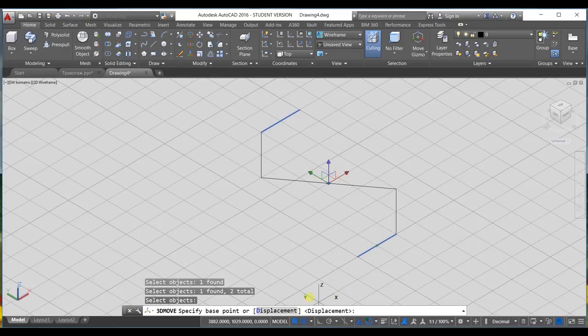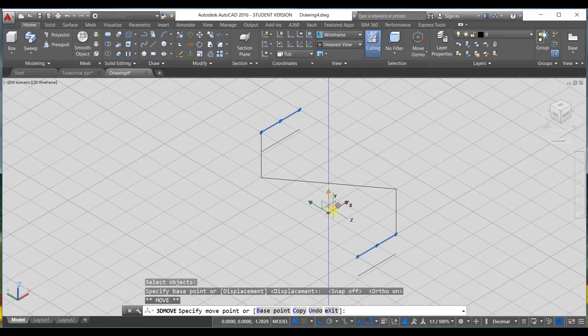and then I'll need the grid snap off, and the ortho mode I'll need it on. I toggle it on. Then I choose that axis, I pull it down, and I type at the command line 1 and I press enter.